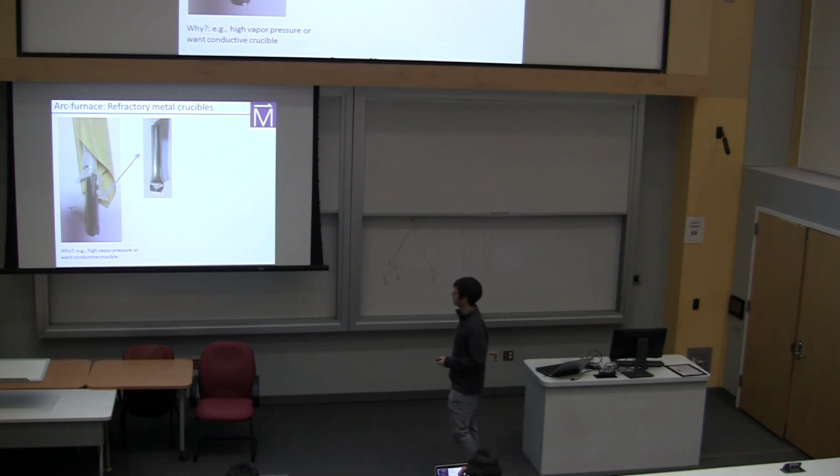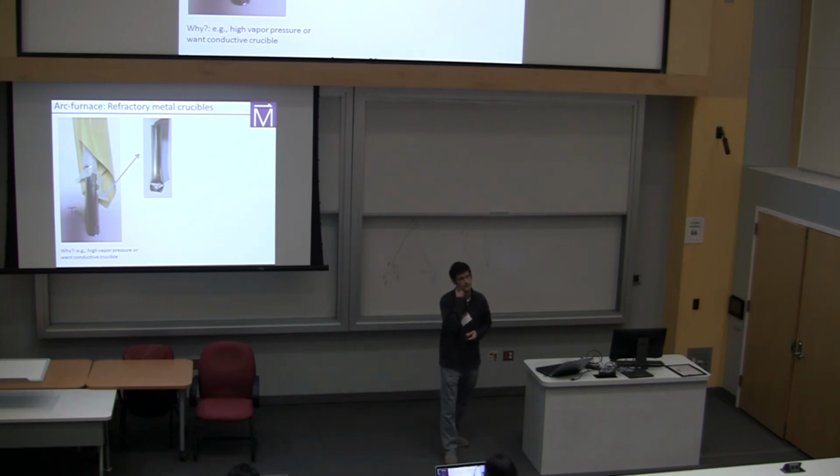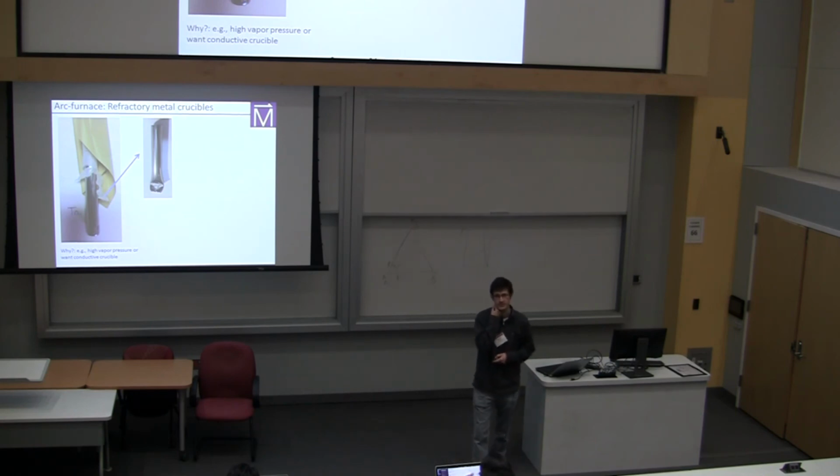So what I tend to do, and I think this is a really good way to do it, is you press the bottom using just a vise or something, and then you make this little fishtail. These ends are bent up, right? So there's a little triangle here, and these are pointing up. And the idea here is that now, when you bring the arc into place over this, you're going to have gravity on your side.